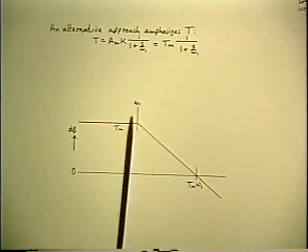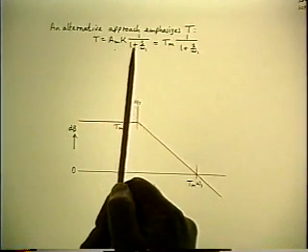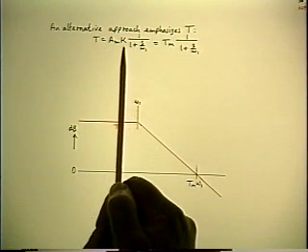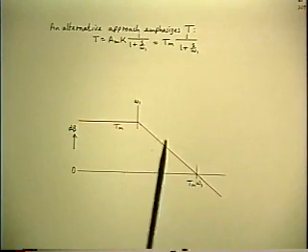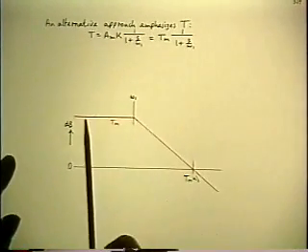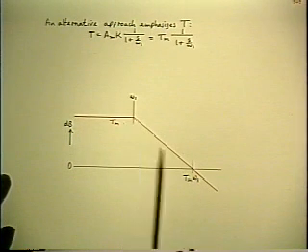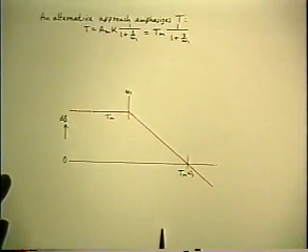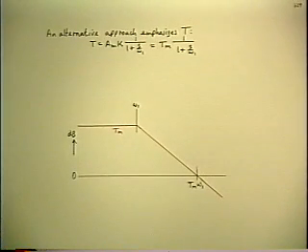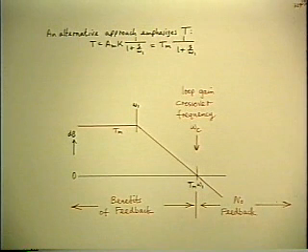representing the loop gain, T is A times K. So if A has a single pole and K is flat, then T has the same single pole. And if you draw the asymptote sketch for T, you have a mid-band value Tm, a pole at omega 1, and then it drops off. Now this time the 0 dB axis is very important, because it divides the frequency axis into two ranges.